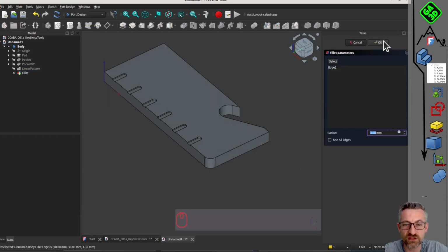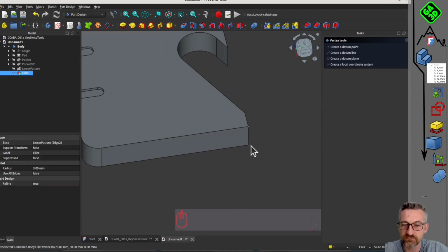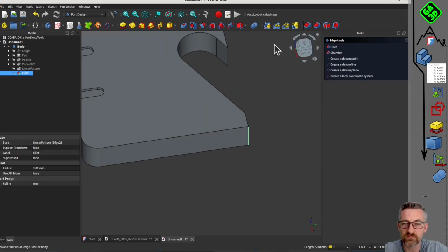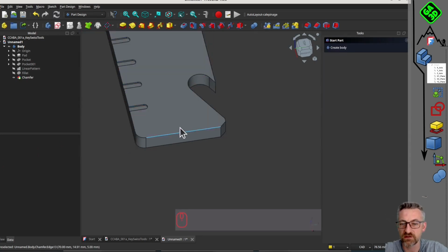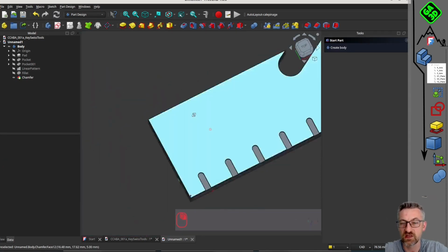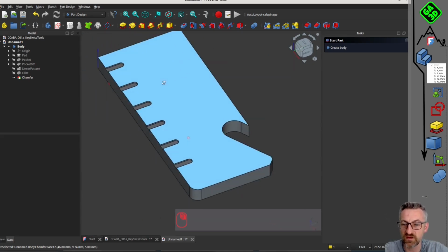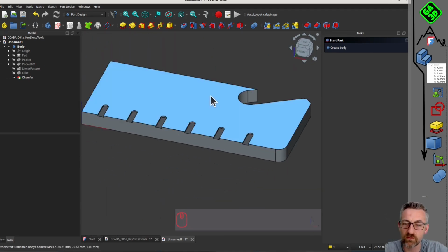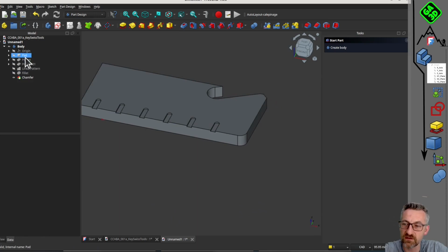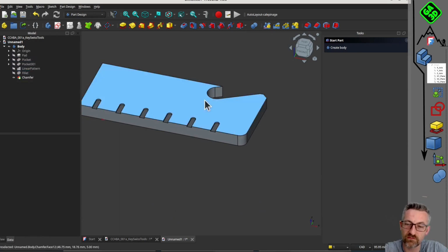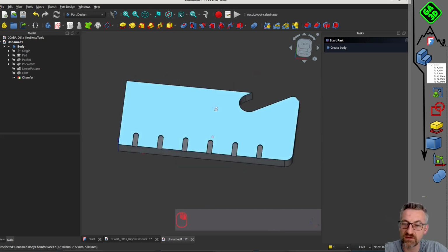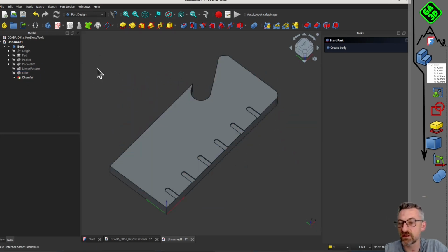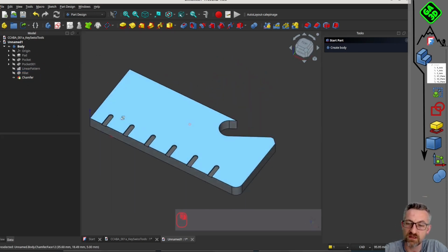So I was saying here, I added the small grinder symbol for finishing operations. What is it? Generally, for the calculation of your 3D shape to go well, we finish with the radii. So notably grinding, chamfering. So you select the edge, you apply a chamfer. You can choose the size of your chamfer here, and you have your chamfer directly. So these are operations. They are always done last as late as possible in your construction tree.